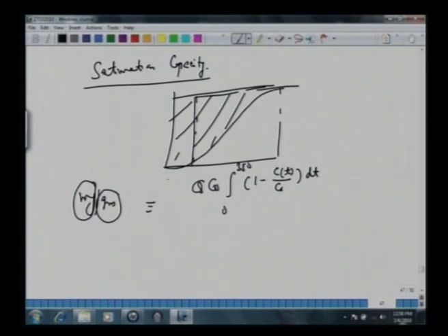Essentially this area under the curve, either you solve numerically, since you know all these data points, making use of certain numerical methods to calculate this area, or even approximately one can measure, assuming that's rectangular, maybe this is very close to the triangle, so half length into height here, divided by the total amount of adsorbent. So all this quantity we know, this Q is 80 cc per second.